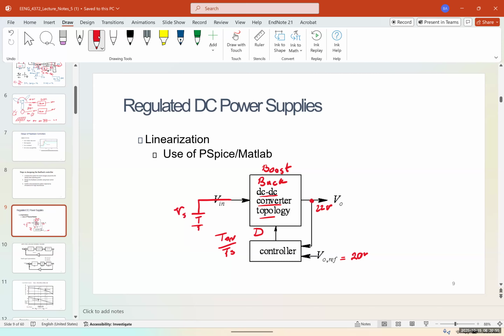This shows an example. Again, I'm not going to go into the proof and depth of it, but this shows an example of the logarithm of the magnitude of T and the frequency response of T. And you can see that around 20 log of K, we have a sudden drop. And this is going to be our cutoff frequency, which is around 0.7 of the maximum that we have. And at this point, we have the corner frequency, and you can see that the angle starts from 0, goes down to negative 45, and finally to negative 90 degrees.